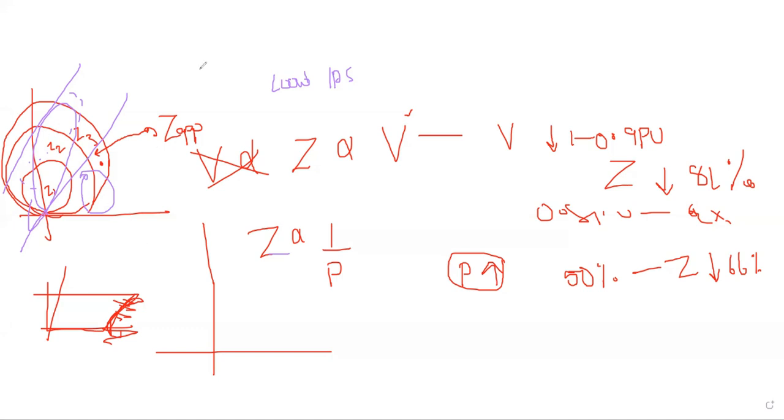Now, this is the characteristic, right? So what I have done is I am saying this is the operation. Whenever the measured impedance is above this, the relay will not operate. If it is falling under this, zone 3 will operate. If it falls in zone 2, or zone 1, this is the case. Now, I am doing some calculation. I will share that calculation with you.